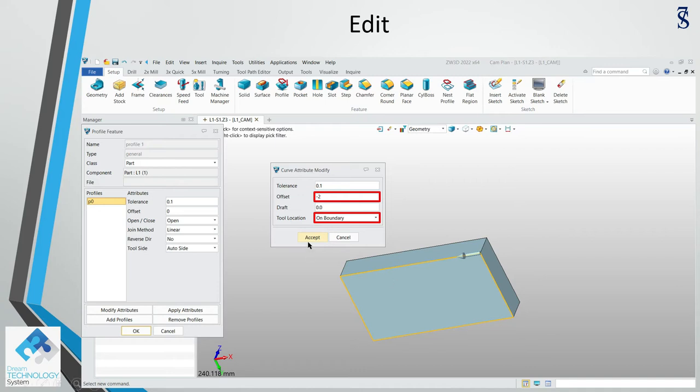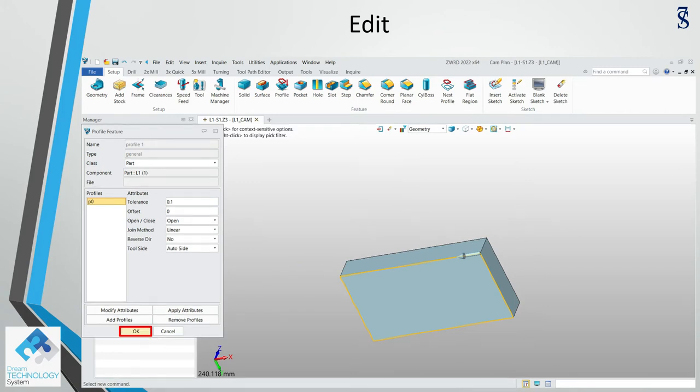And also we need to change the tool location from pass boundary, I think the original is pass or tangent to boundary, to become on boundary. Then you offset 2 mm. That means the tool travels offset 2 mm from the edge, and then it will start to turn direction to another tool path. Let us accept this one, and then we click OK.